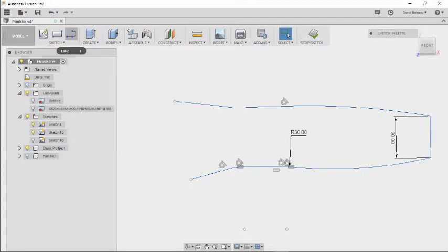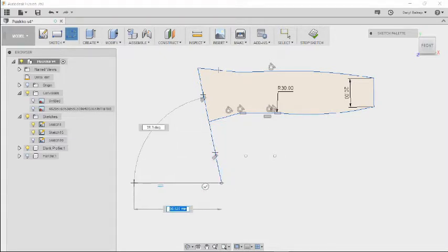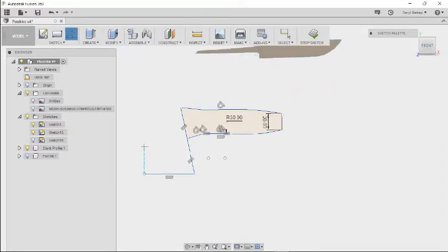This time I'm going to draw a line from here to that point. Left click again, continue the line function. And you see those two hash marks, right there towards the center of the line segments. Those two lines are parallel, which is what I was after. Alright, we'll just go over here a good amount. I'm just creating a tool to cut the back of the knife off.